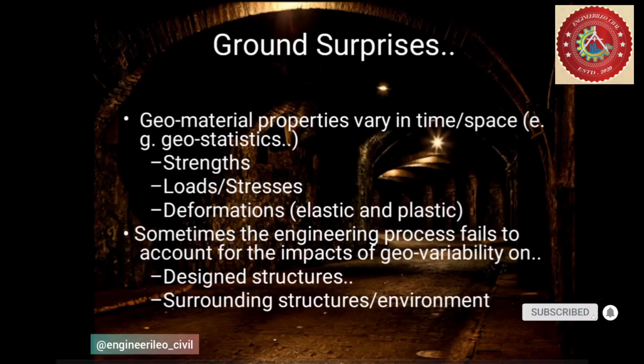Now we are going to learn what problems are encountered during construction of tunnels, right? First is ground surprises. Of course, we are constructing tunnels underground, so the ground is the main trouble that we encounter. Geomaterial properties vary with time and space: its geostatistics, strengths, loads, stresses, deformations. Of course, it will vary from soil to soil. Sometimes the engineering process fails to account for the impacts of geo-variabilities on the design structure and the surrounding environment.